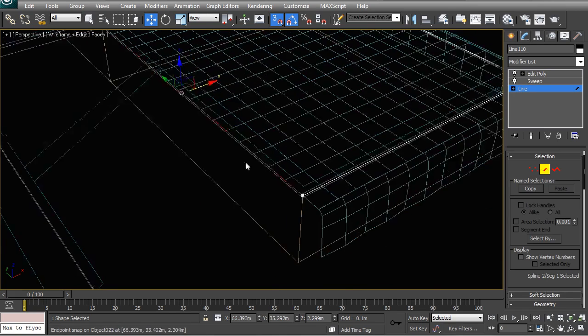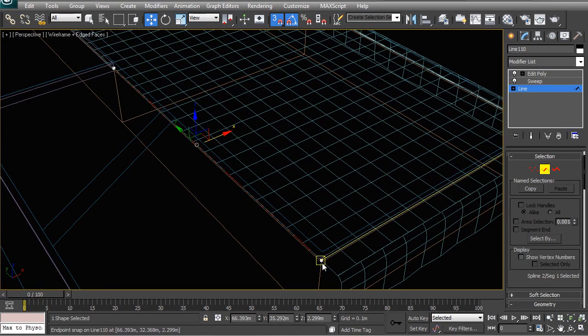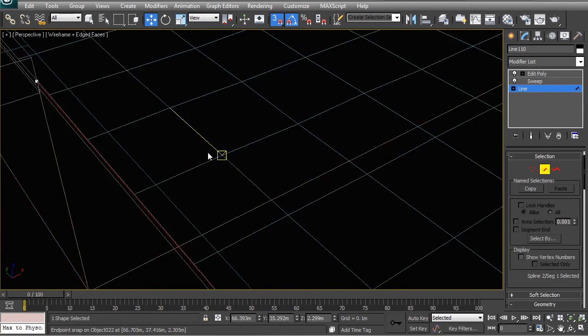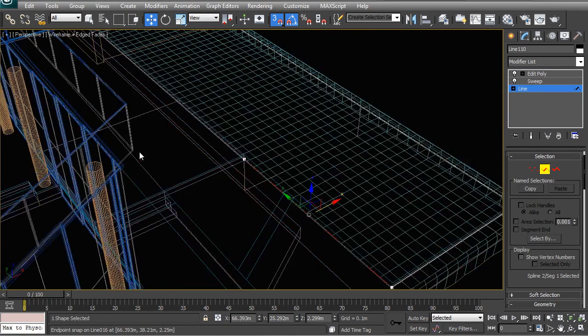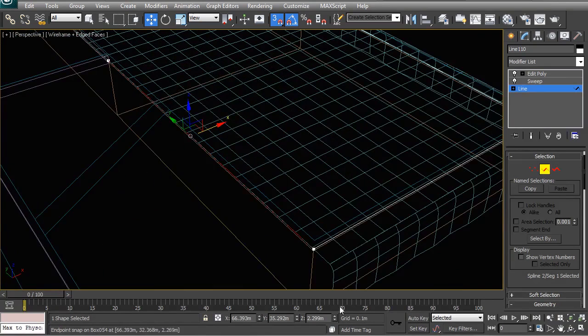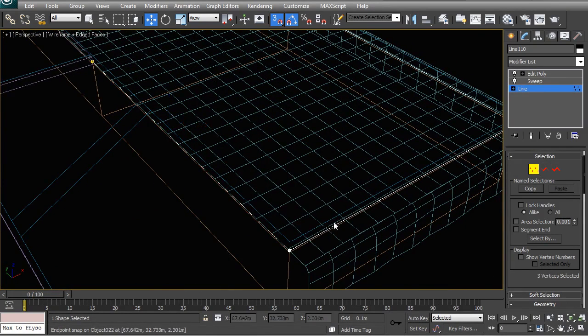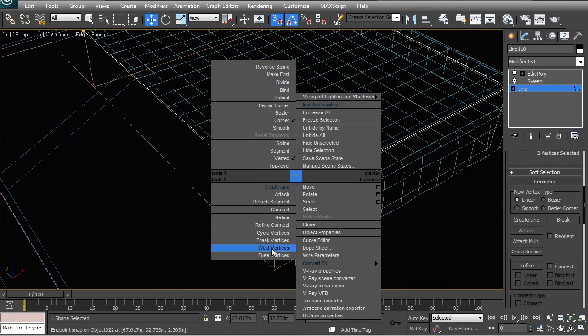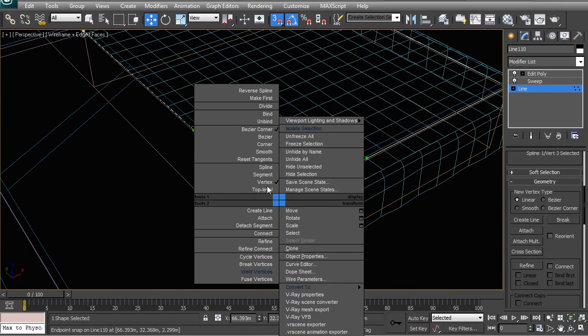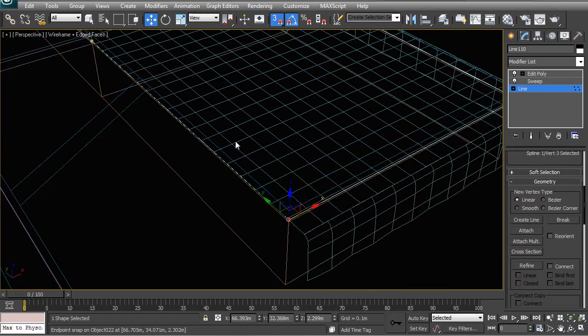place. If you are able to, you can also snap onto this point originally and then snap onto something here, but I don't actually have any object to snap it onto here. This is basically floating in space. That's why I used a reference object right below. Next, I'm going to choose these two vertices, and you can see that there are two selected, and I'm going to right click and weld them together. Then I'm going to right click again and choose corner.